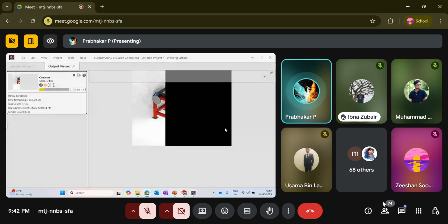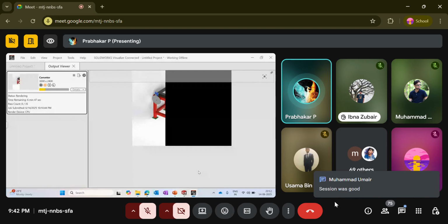So you are looking for this: if you right click on the angular line you drew, it will ask whether to make it vertical or horizontal, and you can use that. Or if only one line is parallel, you can select that line, press Control and click on the new line which you want to make parallel, and it will automatically become parallel.